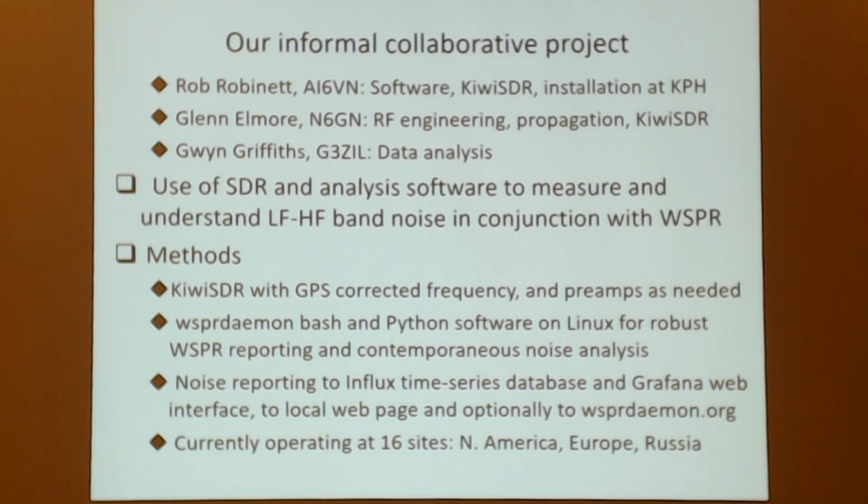In Whisper reception, there's a 2-minute long packet cycle. And the Whisper Daemon, like WSJT-X, records a 2-minute long wave file, a 12 kilosample, 16-bit wave file, and hands it off to a Whisperd utility provided by Steve Franke, which extracts the signals, the Whisper beacons that we're transmitting during that 2 minutes.